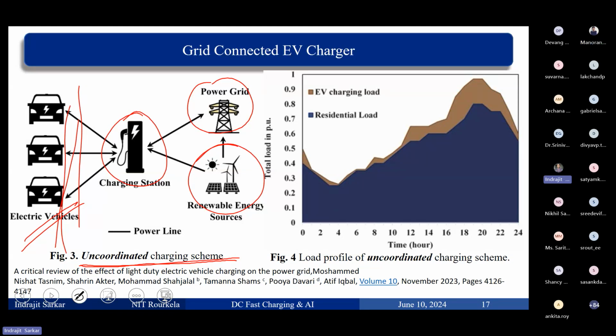So that is why when there is active power consumption from the grid, electric vehicle charging means they are going to take active power. I will talk about this active power. So it is going to affect the grid frequency. If the electric vehicle amount is not significant, then it is not going to affect the grid frequency significantly. Now, I always talk about active power. When we are charging the vehicle, the active power is consumed by the battery. It is mandatory that the charger that you have built takes only active power from the grid, not reactive power.